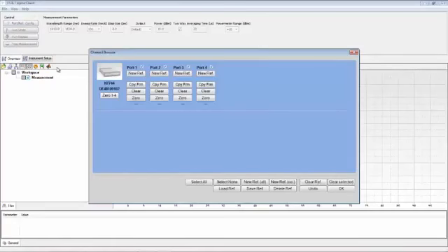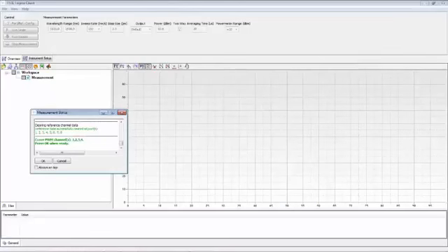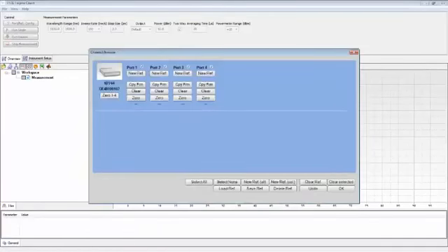The first step is to zero all the channels of the power meter, and I've already covered the input, so I can select zero channels 1 through 4, and it goes out to initiate the zeroing. The process of zeroing takes about 15 to 20 seconds per channel, but it ensures that all dark offsets are removed from the power meter channels.